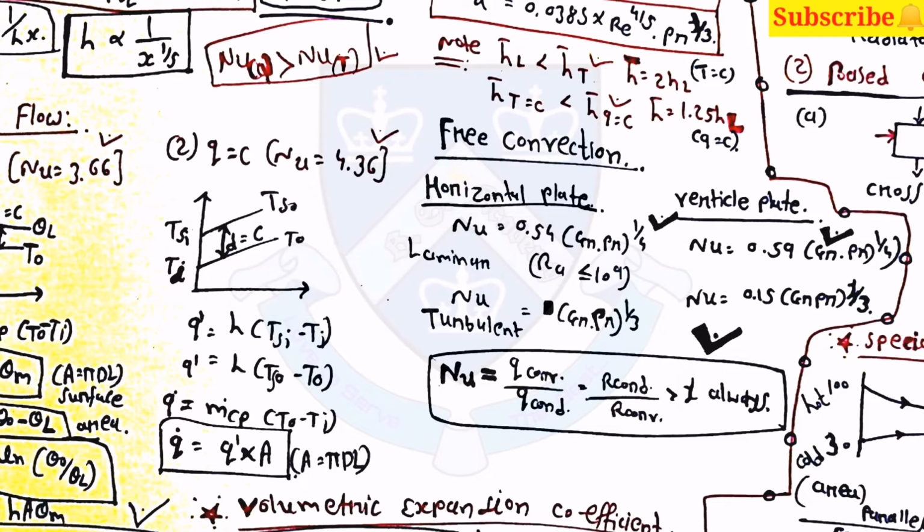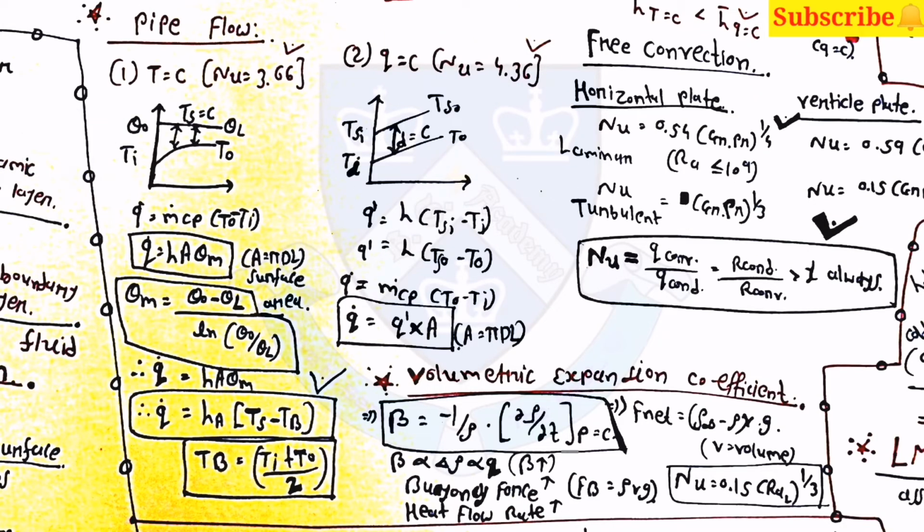Then for the free convection, the equations of the horizontal plate and the vertical plate are given there. You can take a screenshot. Then here Nu is equal to Q convection by Q conduction, which is equal to R conduction by R convection, which is always greater than 1. Then for pipe flow two conditions are there. First one is for T equal to constant, and in the second one Q is equal to constant. So you can take a screenshot for those equations also.